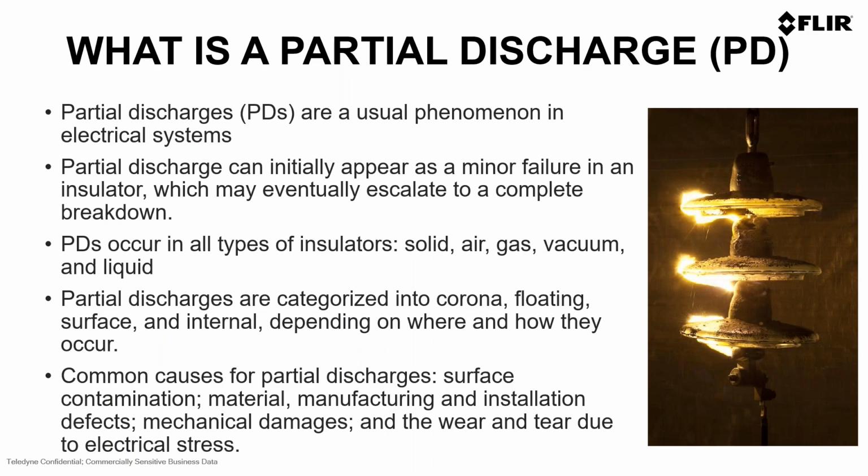Yes, so partial discharge is one of the main applications that we are solving with the camera. Partial discharges are a usual phenomenon in electrical systems. They can appear, for example, as a minor failure, but this will always escalate and progress even to a complete breakdown. Of course, partial discharges occur in different types of components, specifically in medium or high voltages.